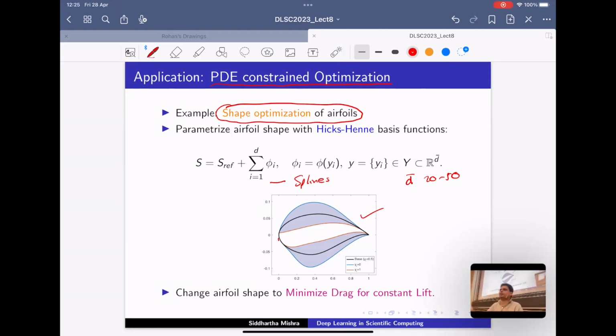You start with something which is looking reasonable, and in aerodynamics, it's always teardrop shapes, because these, as we know, are sort of streamlined. So this is a shape which is what is called a base shape, the one that I'm just drawing now. Okay, so now the idea is that you have all these possible shapes, so you perturb these shapes and you are inside this design envelope. And then you don't want the shape that is at the margin, right? This is not going to give you a good flow. This will be too flat and too non-streamlined.